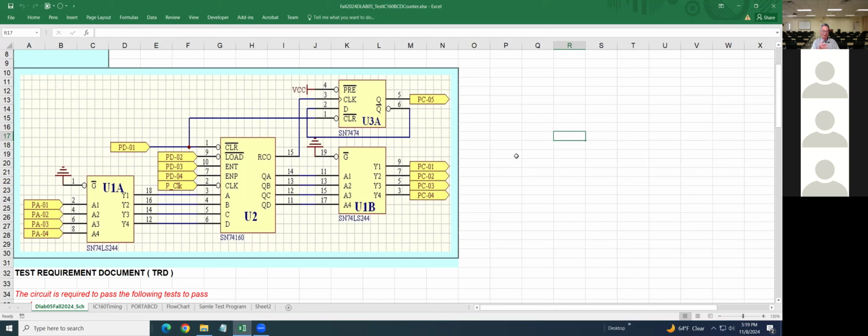The thing in the company, the circuit board is already built. However, the wires are in the middle layers, so they cannot be broken. The only thing that can be wrong will be either U1 or U2 or U3.